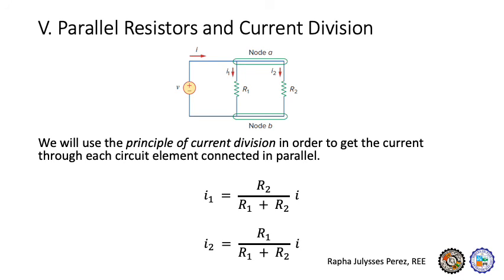Borrowing from Ohm's law again, where I is equal to voltage divided by resistance, current I is inversely proportional to the value of resistance R when voltage V is constant, and voltage is constant in a parallel circuit. Hence, the larger current flows through the smaller resistance, or the path of least resistance, as you've probably heard somewhere. You need to remember this because these are simplified approaches to calculating the voltage division and current division for series and parallel circuits.